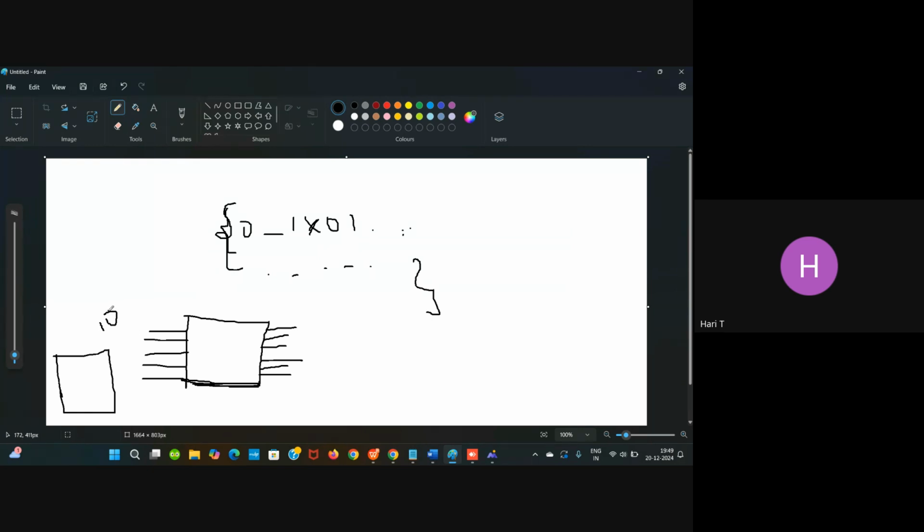I think in the previous session they might have discussed the pads, the physical design or physical verification. Any of the audience? Yes, sir. There will be the IO models outside our design, pad IOs, and each in-out pin will be connected to the pad output. The IO, we call it as IO ring. So what ATE people do is they program this IO before implementing the ATE test.